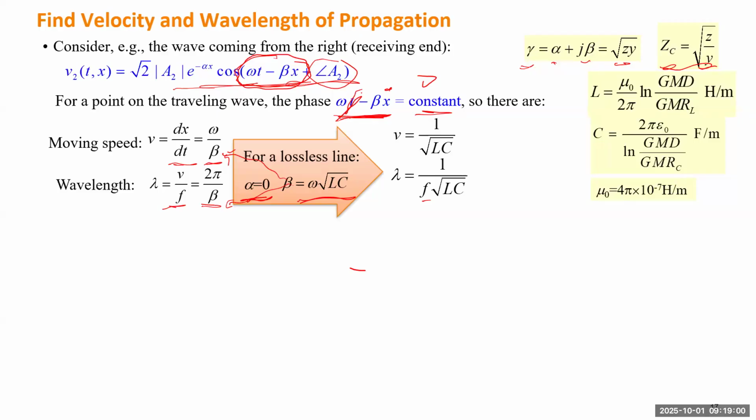So let's go back to the formulas calculating the L and the C from the line parameter sections. We know the L and the C only depend on the geometry of the line, not the material of the line. If we know the geometric mean distance, which in a three-phase line is the separation between any two phases, we can calculate a GMD. If we know the radius of the conductor, even if many conductors together make a bundle, we still can calculate